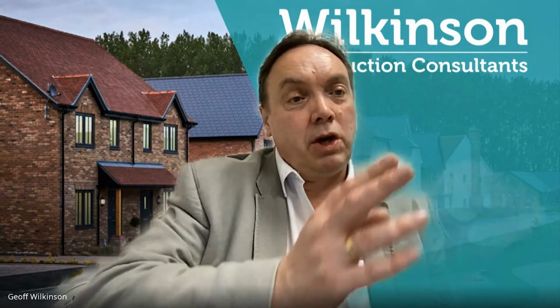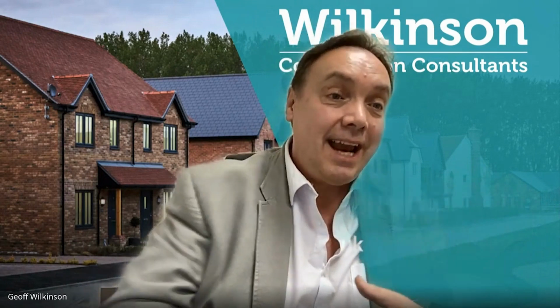Any of these, if you've got a cavity wall, will cause any moisture coming down the cavity to potentially run into the building rather than out of the building. So that's where you would be looking to have what we refer to as a cavity tray in place, which will divert any moisture coming down the cavity outside the building. And whenever you have a cavity tray, you should always have a weep hole to ensure that the moisture that comes down can actually be directed outside and away from the building.